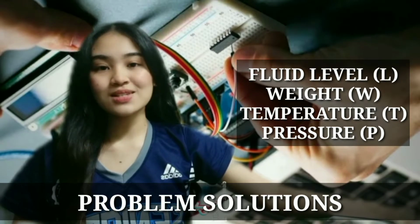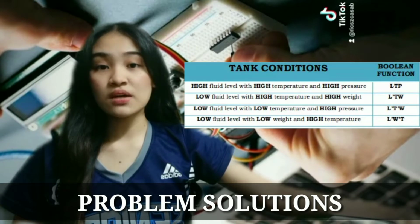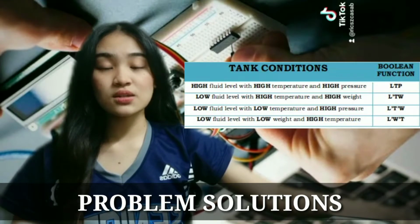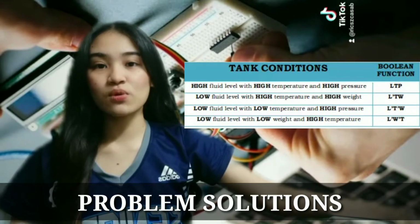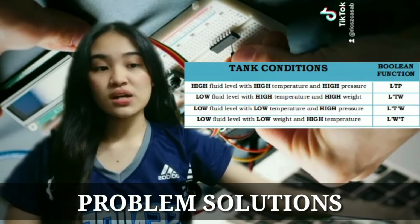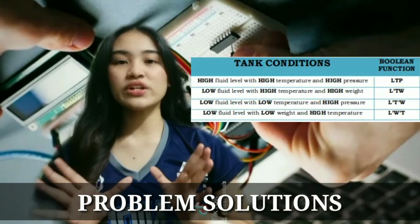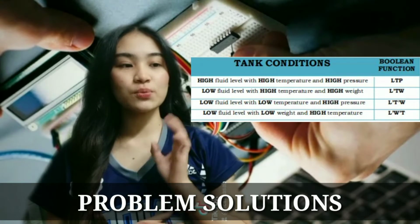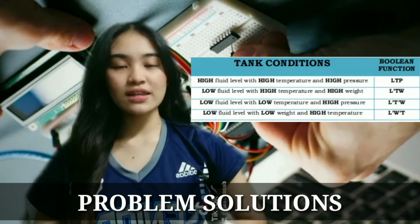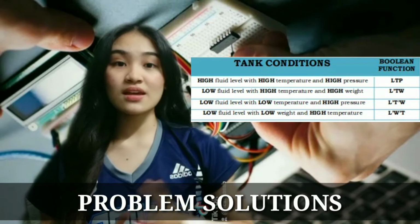For our Boolean expressions for the 4 conditions, we will be considering LTP for the first condition, wherein L is at logic 1, T is at logic 1, and P is at logic 1, meaning the temperature, the pressure, as well as the fluid level are all high. For the second condition, we will be considering the Boolean function L'TW, wherein the fluid level is low, the temperature is high, and the weight is high.